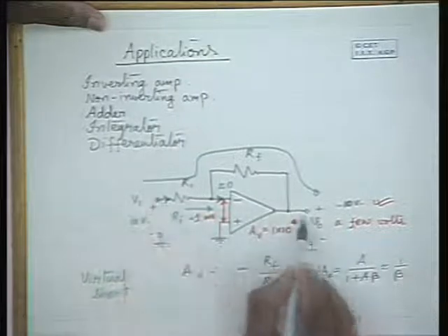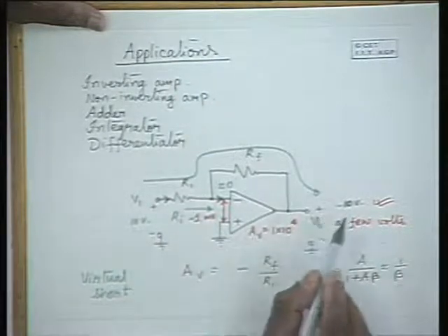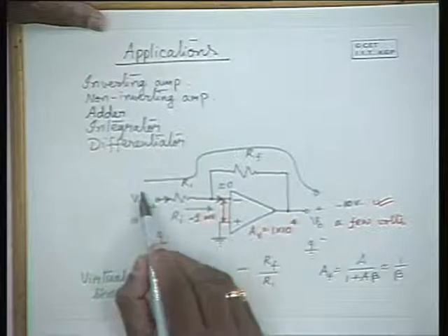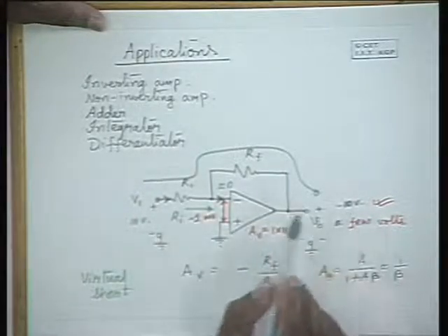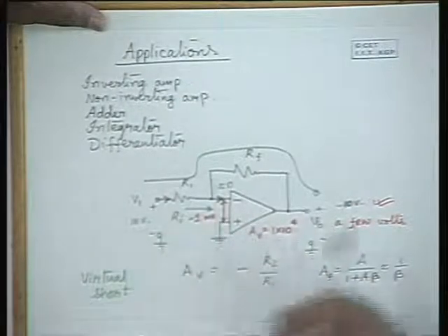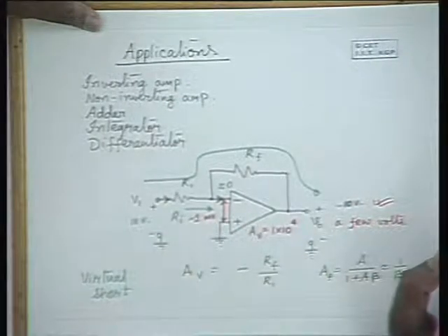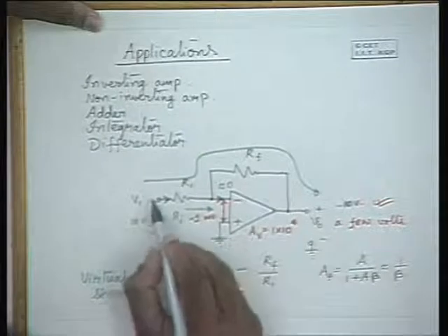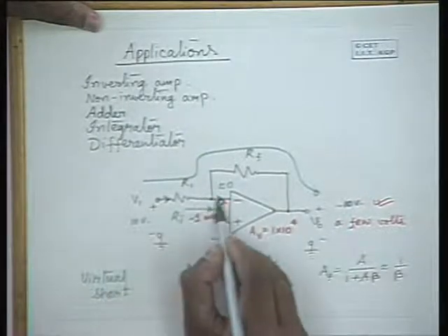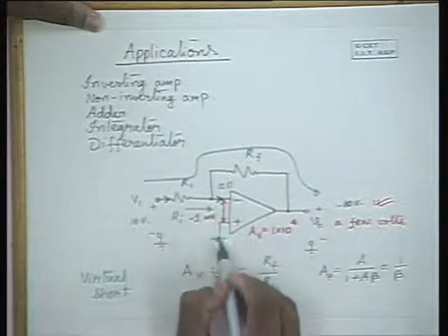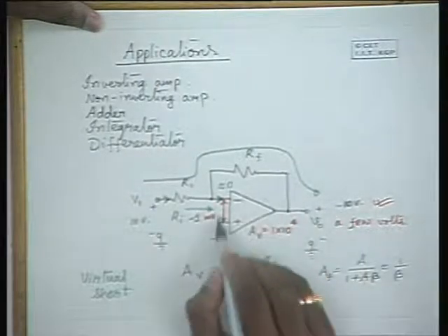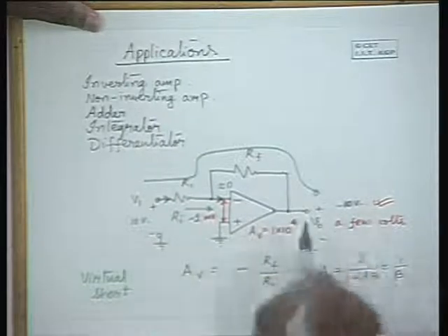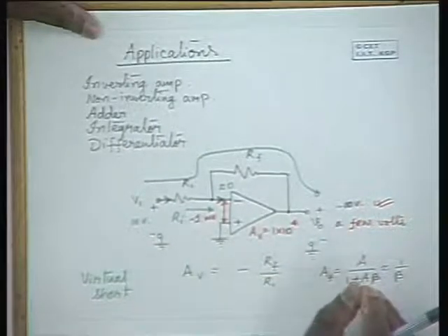So from 10 volts it will flow to minus 10 volts, and the 20 volts gets dropped across R1 and Rf. And in doing so, this drop will make it equivalent to almost the ground potential, so that in spite of high gain, you will get a reasonable output voltage.